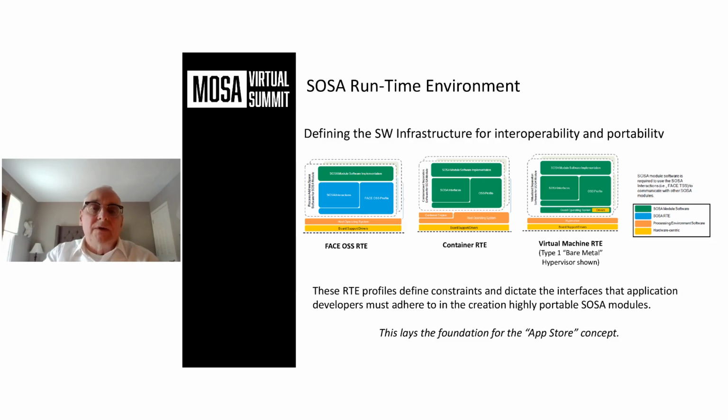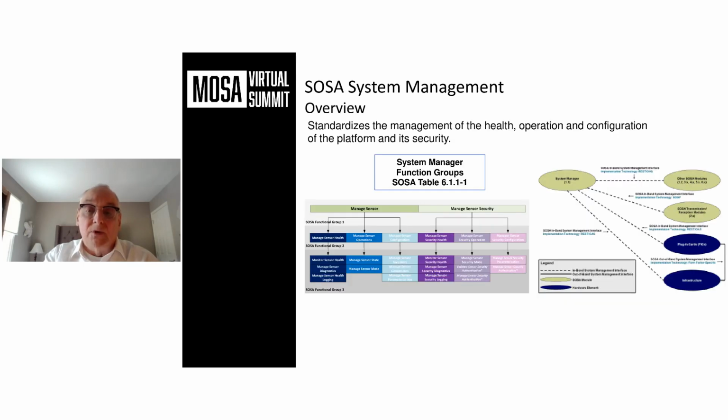But before we get to that, we look again at standardization that's being promoted by SOSA for the RTE being the runtime environment. And here, different configurations of the RTEs are described. The one that's interesting today that's being looked at quite a bit is container RTE that allows us to modularize software using container architecture in the runtime environment. Further, you might need to use virtual machines, and the virtual machine RTE is also defined within SOSA, including examples of the hypervisor. What this leads to is more like an app store sort of concept around SOSA software, where software will be modular and much easier to operate out of the box than if these things are left open and not defined. So this helps with interoperability and portability.